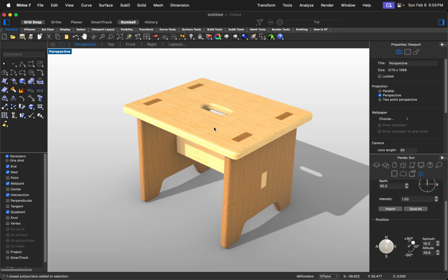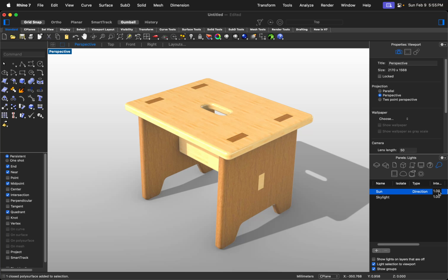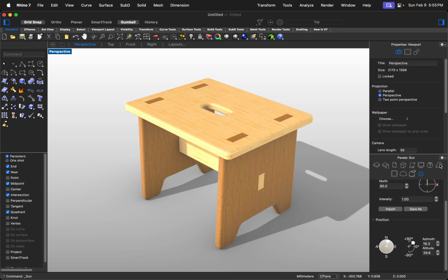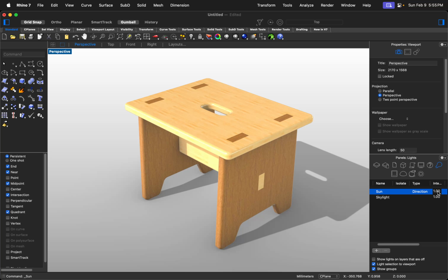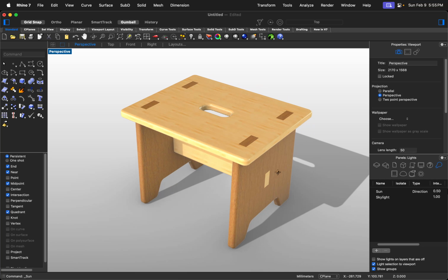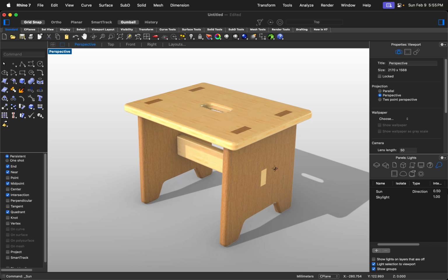And notice the sunlight looks a little bit too bright, and that's because by default the sunlight is in full blast. One means it's 100%, so I will actually lower the sunlight. Let me click on it. So 0.5. And that will drop the sunlight so that it's not so glaring. Okay. And then if I'm happy, this will be the preview of the product rendering.